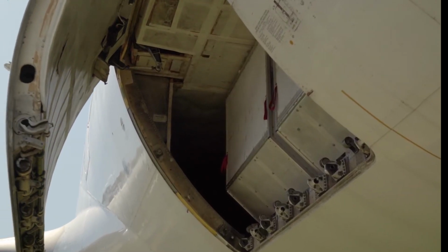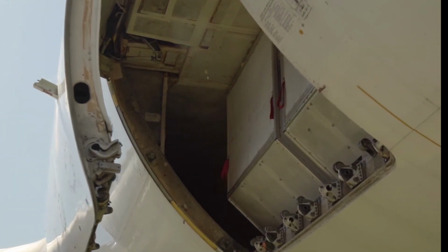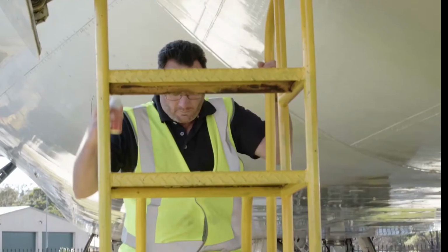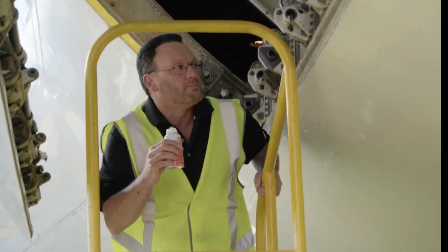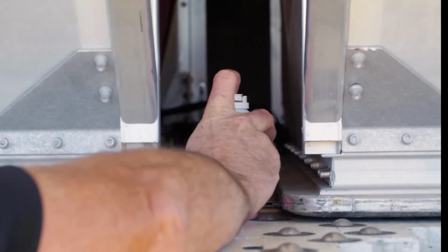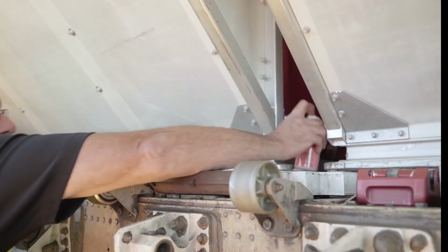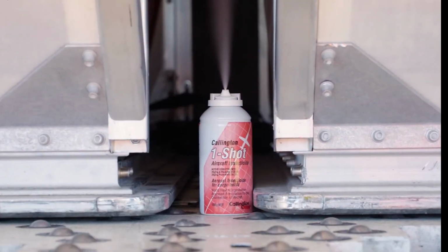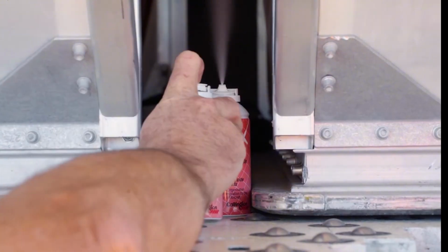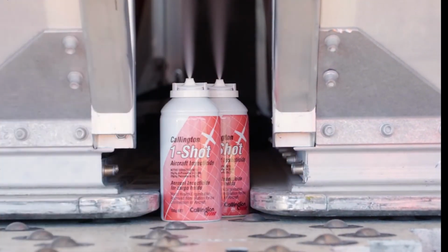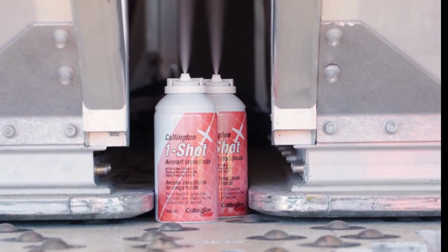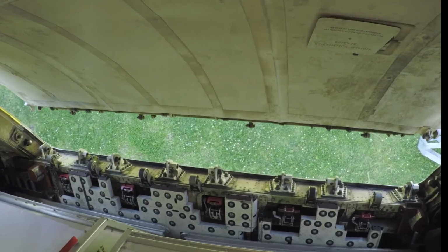As the lower cargo door is being closed, leave just enough of an opening to stand a single one-shot can between the cargo containers. Hold the nozzle down to activate the aerosol. If more than 1 can is required, repeat this application method with additional product. When you see that the spray has been activated, close the hold door immediately, leaving the cans in place to complete the disinsection process.